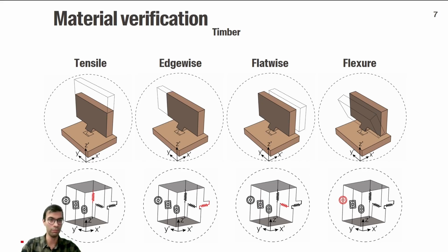Or alternatively, we can simply define the dimension of the wood-wood connection. Specifically, I'm talking about this area here, and simulate this area as a simple beam element in our structural model.